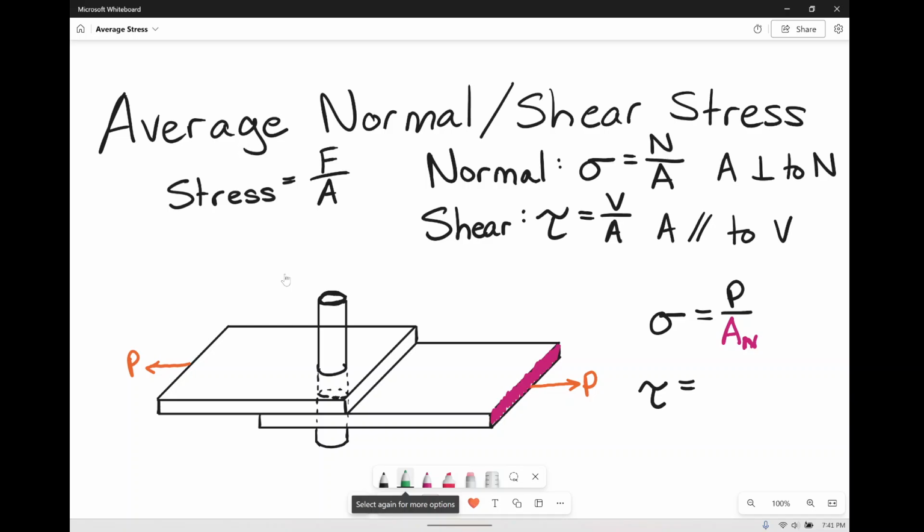I think it's easier to not think of it as your fist because that's going to do radical damage, but effectively take a straw and try to punch it through the wall. If you do that, obviously there's going to be a hollow area where you've punched the straw, but the damage is literally going to be the size of the straw, or perhaps a nail or something, right? It's not that big. And the reason is because what's causing the shear is that force that's going down across the area face there. So effectively, what we're looking at in other terms is two plates sliding in opposite directions.